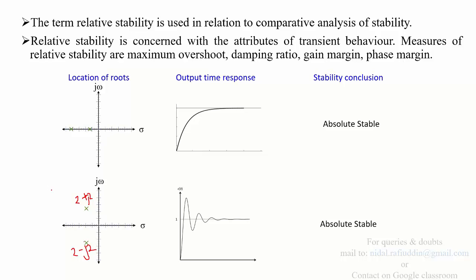So suppose that in the same system you are given a pole located, let's say, at 5 plus 3j. This particular pole will always have its conjugate somewhere at 5 minus 3j, or in other words, complex poles will have a mirror image about the real axis. So these two conditions are absolutely stable: when you have poles lying on the left half of the S plane, or they exist in complex conjugate form.